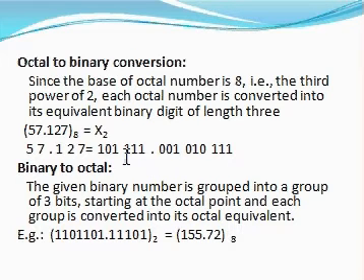And to convert the binary into octal, the bits are grouped into 3 from the LSB. Here this is the LSB. Here it is grouped into 3, 1 0 1, and the octal equivalent is 5. In this way, all the binary bits are grouped into 3, and their octal equivalent is written here. This is the method to convert binary to octal.